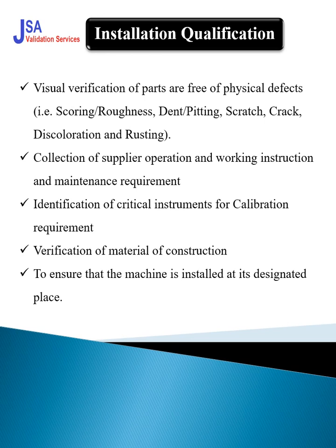Visual verification of parts: they should be free from physical defects like scoring, roughness, dent, pitting, scratch, crack, decoloration, and rusting. All should be free from any physical defect. Collection of the supplier's operation, working instruction and maintenance manuals. Identification of critical instruments for the calibration requirement.